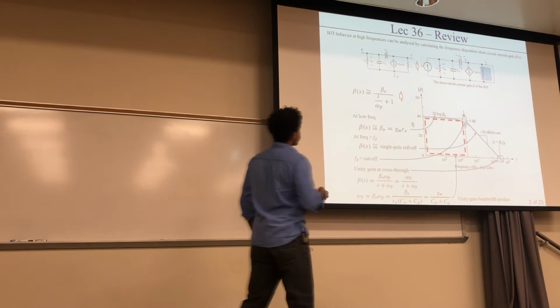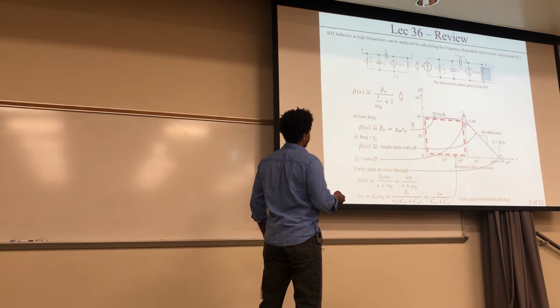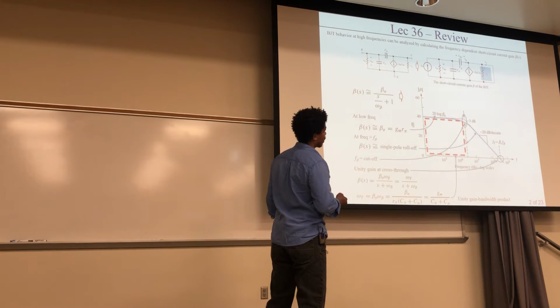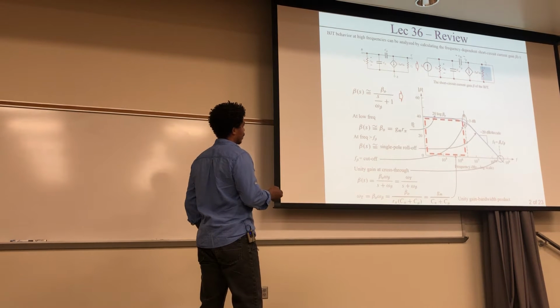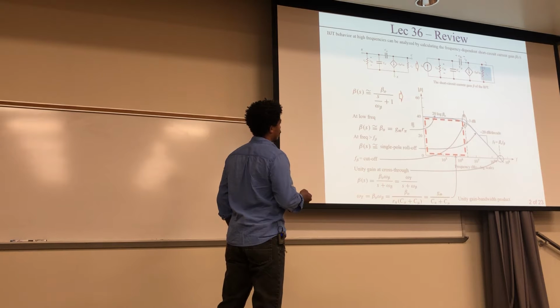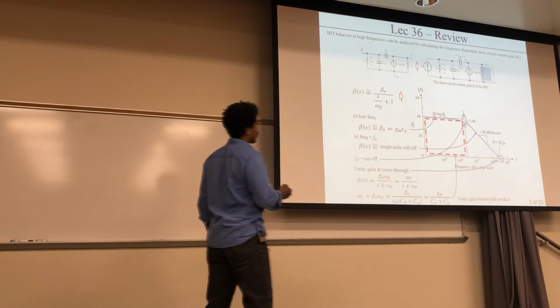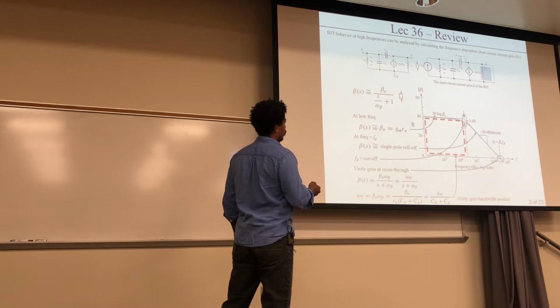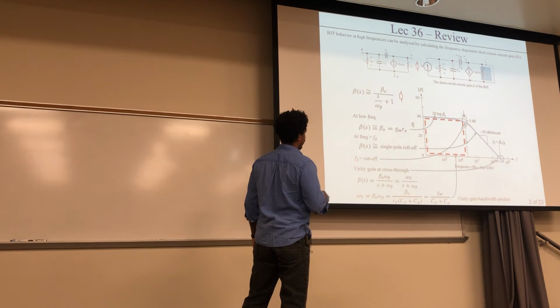At higher frequencies, there's a single pole roll-off at 20 decibels per decade, when your frequencies are much higher than your cutoff. At cutoff, at this frequency right here, the gain is 3 decibels down from the max amplitude. The point where that happens is the cutoff, determined by f beta or omega beta.